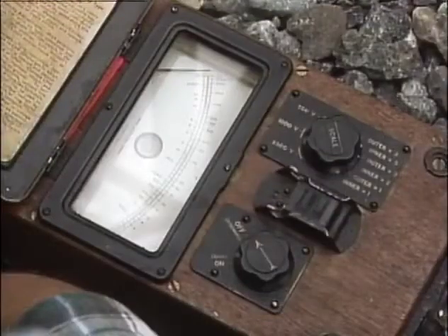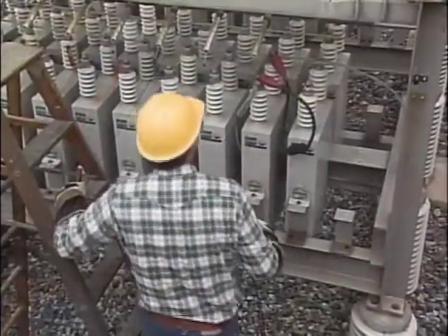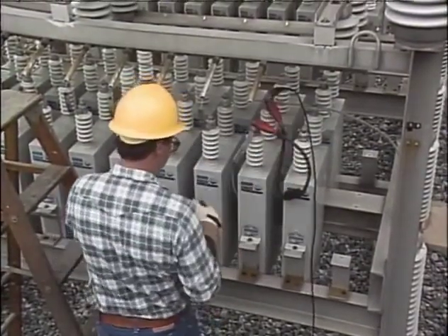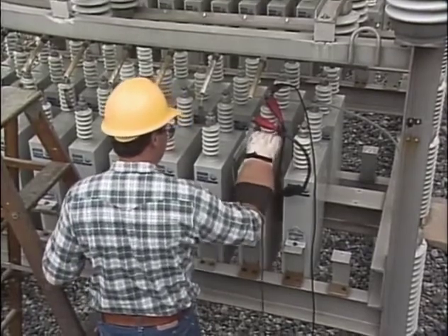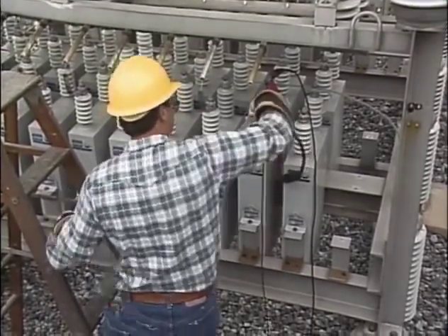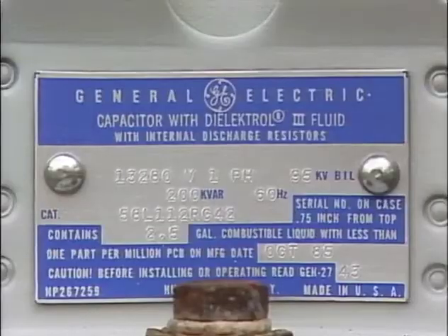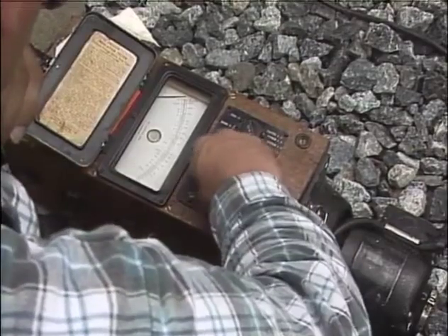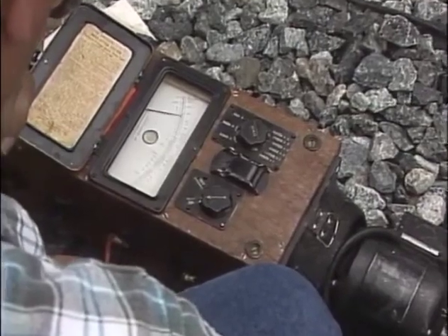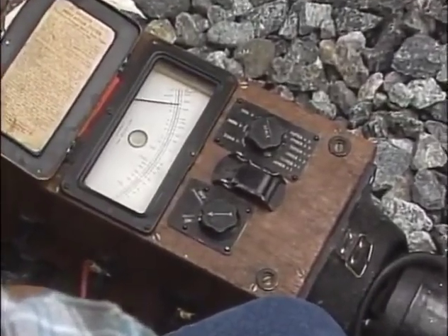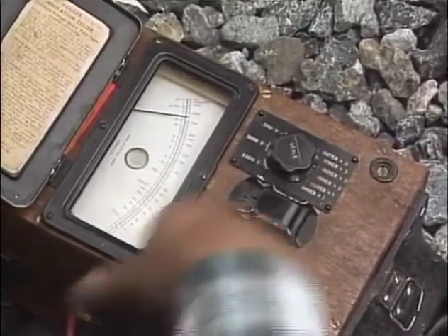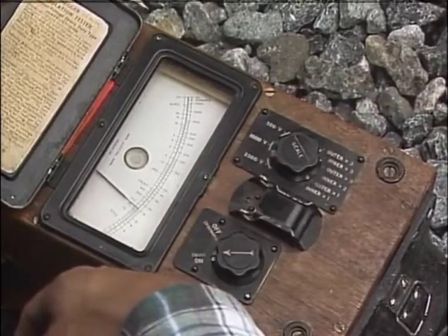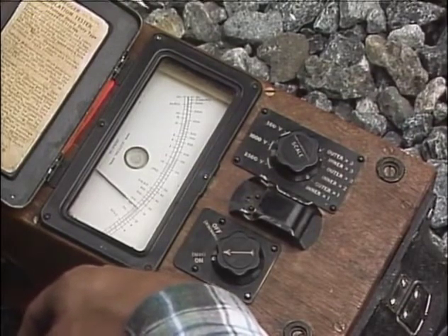When a bleed resistor is tested using a megohm meter, the megohm meter is connected the way the multimeter was connected. One lead is connected to the neutral terminal of the capacitor, and the other lead is connected to the normally hot terminal. Then the short is removed from the capacitor. The nameplate of the capacitor is checked to determine the unit's voltage rating. The megohm meter is turned on to apply voltage to the capacitor and get a resistance indication on the meter. The voltage is increased a step at a time up to the voltage recommended by company procedures, but without exceeding the rated voltage of the capacitor.